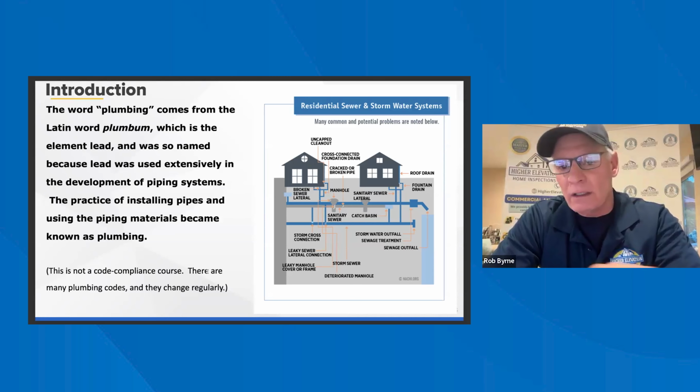Water pressure, these are the things that would affect it. Obviously, we just talked earlier about the size of the pipe, the material, which would cause friction, changes in direction, pressure, and elevation. So those are all things that would affect it. Like we were talking about, if you were doing a functional flow test and you turn the water on downstairs and then go upstairs and turn it on, it would drop even more. Sometimes you don't even get any.